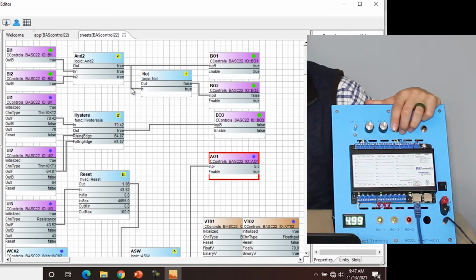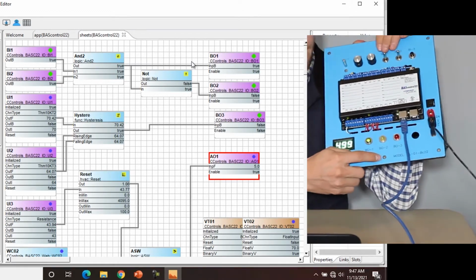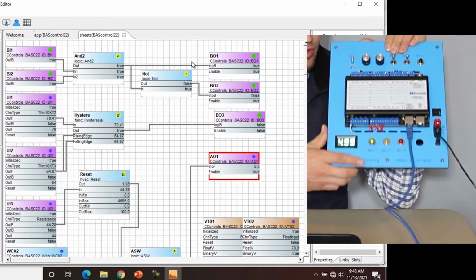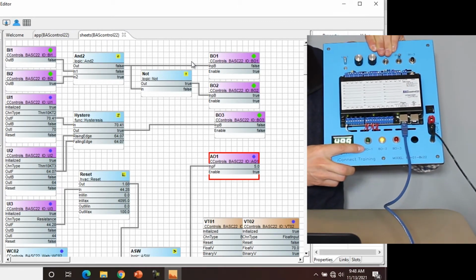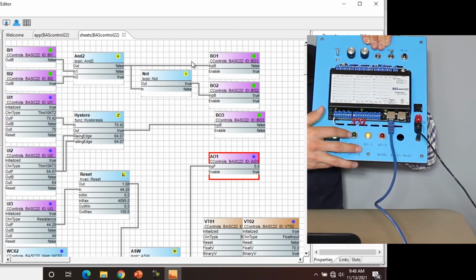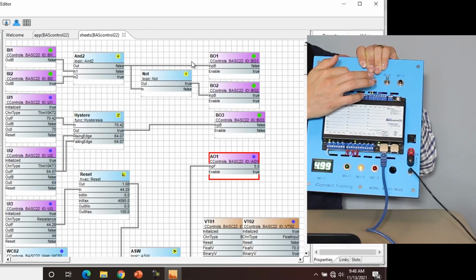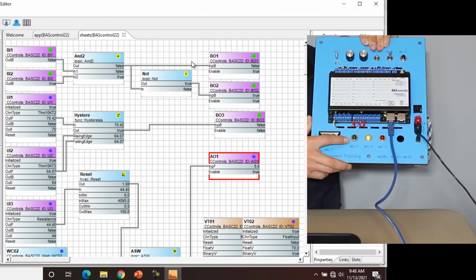If we follow the link, it goes to the NOT in, which is true. So the out of the NOT is false. Binary output 2 is false. And if you can see down here, the lights, binary output 2 is off right now because it's false. Binary output number 1 is true. If I click one of these off, you see the green light turned off. That's binary output 1, because now that input is false. That's feeding off of the AND. So if both 1 and 2 are true, then it'll turn binary output 1 on, energizing the light, and the green light would come on.